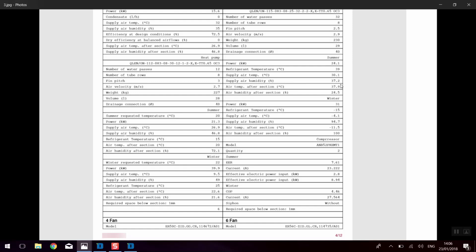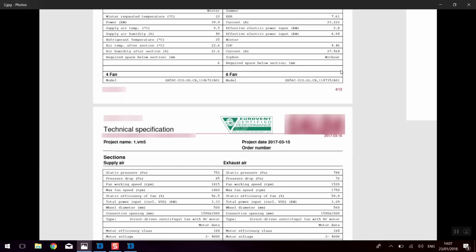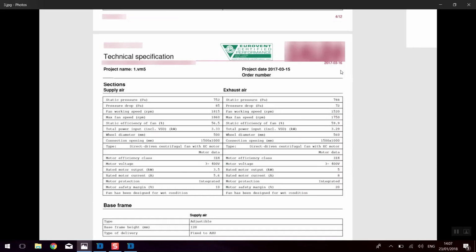And the refrigerant temperature is written as 38 degrees, which at this face velocity of 2.9 is very unusual. Here we expect the condensing temperature, the refrigerant temperature, even higher than 55 degrees, which will affect the whole calculation for the refrigerant circuit in cooling mode. So all the rest looks okay.